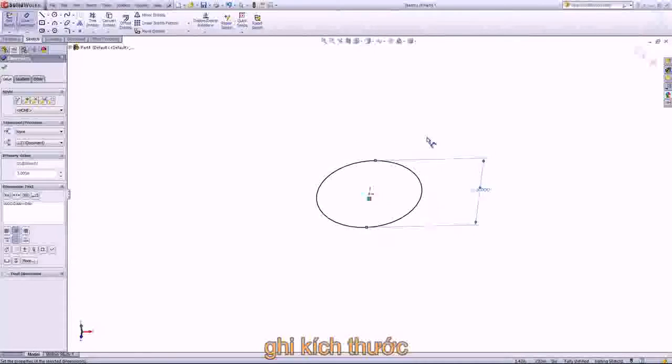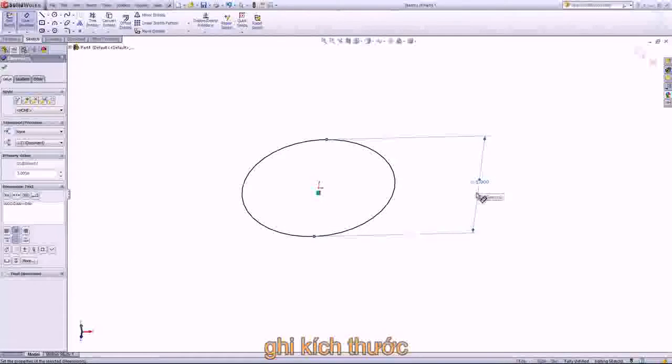One thing to keep in mind when setting this diameter is where you're going to place the profile. In this case, we're placing our profile at the center of this line, which means that it's actually going to be slightly wider than 3 inches. So you just want to keep that in mind when creating your springs.